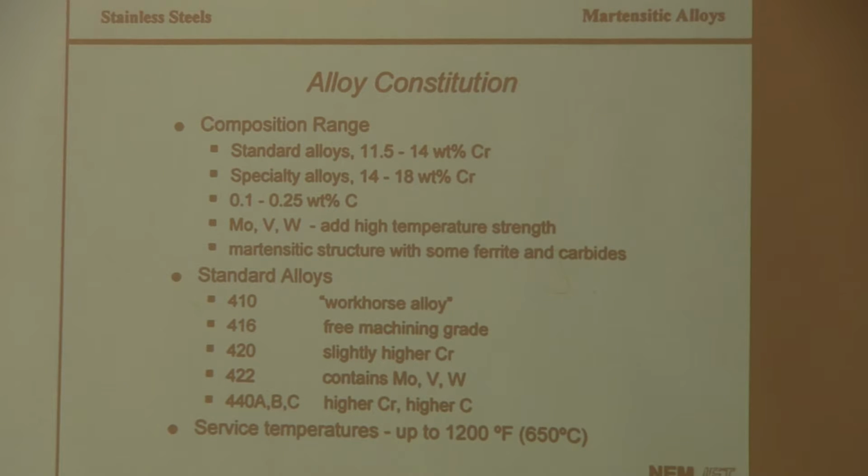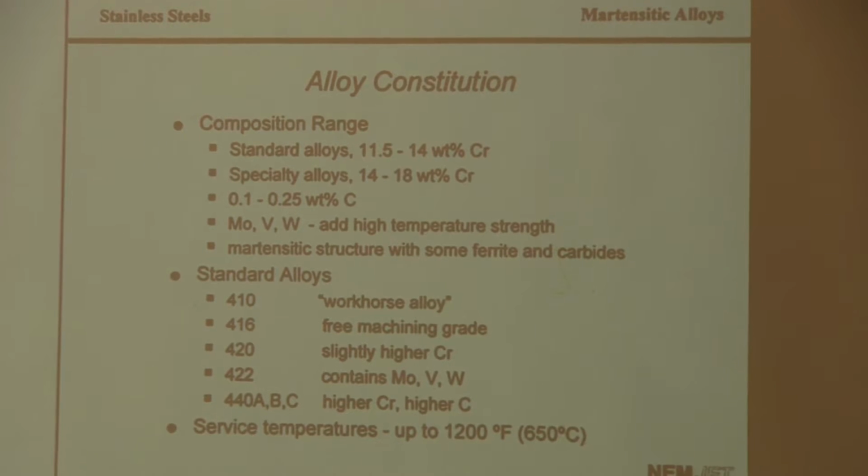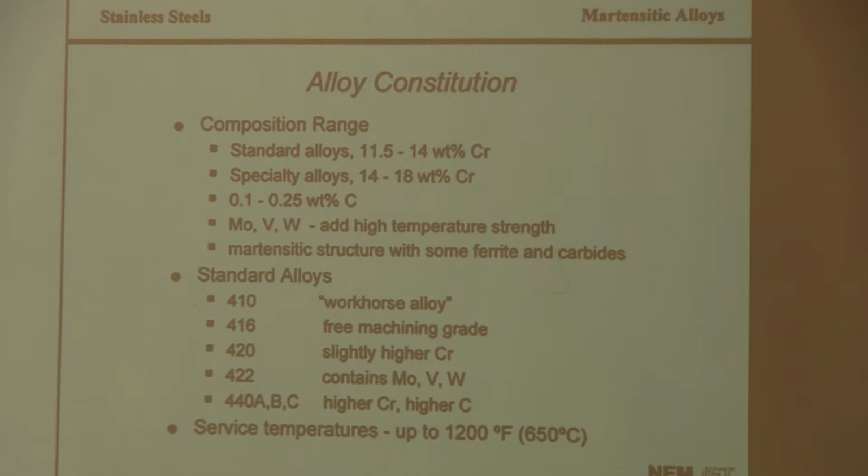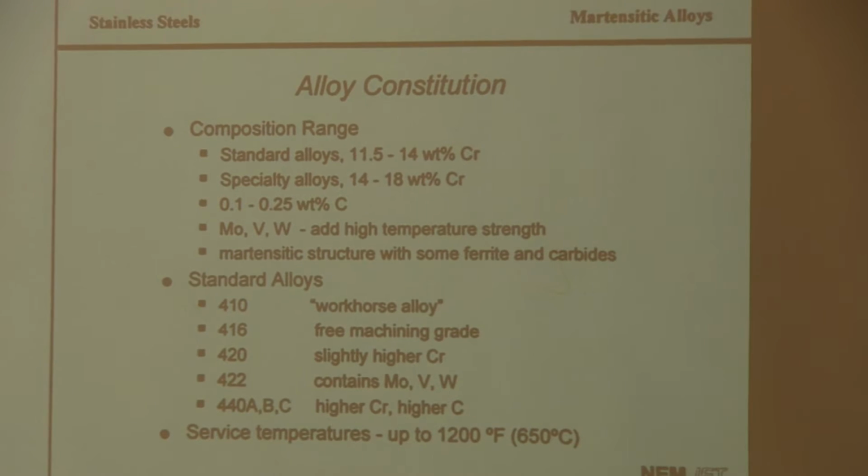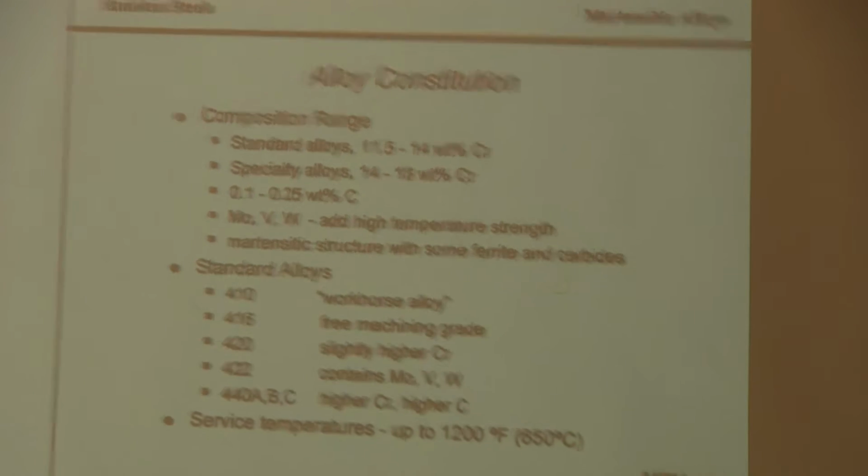One of the limitations on martensitic stainless steels is the service temperature, only up to about 1200 degrees F or 650 degrees C, and that's just because you start to lose both corrosion resistance and mechanical properties above those temperatures.